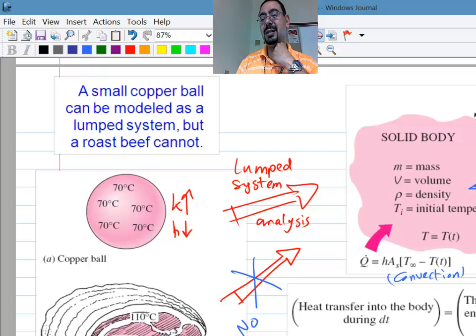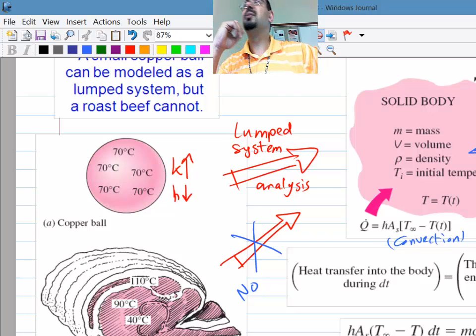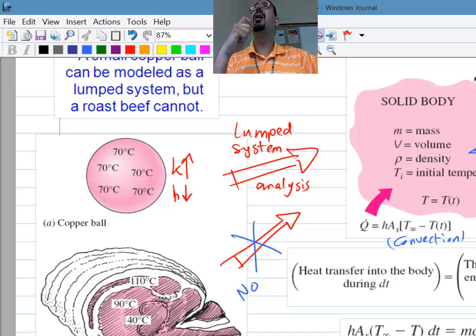So what determines this? It's K, right? K is the conduction, but also it must have how this thing is being heated or cooled. Why is this piece of meat being heated on the grill? Convection on the outside, right? So it's a competition between how quickly the convection is heating the edges, or cooling the edges in case we're freezing it, and how quickly the K manages to bring that new temperature from the edge into the center line very quickly. All right?